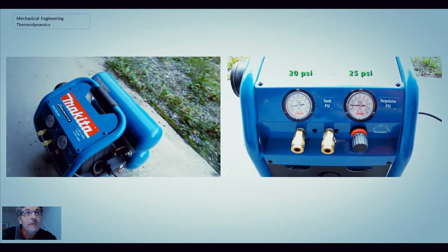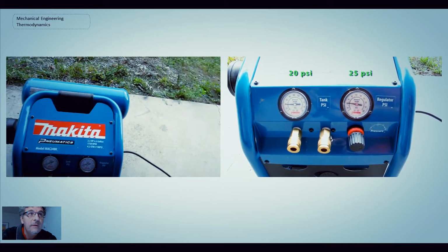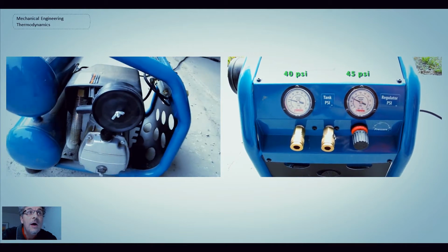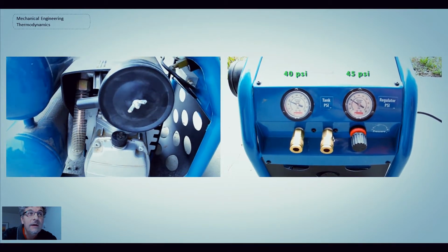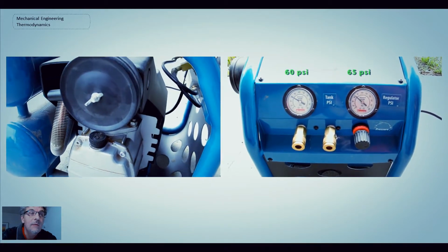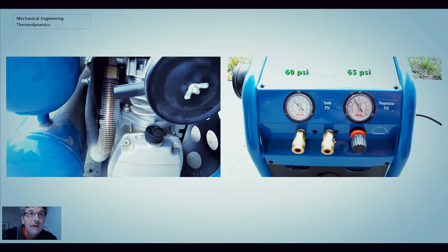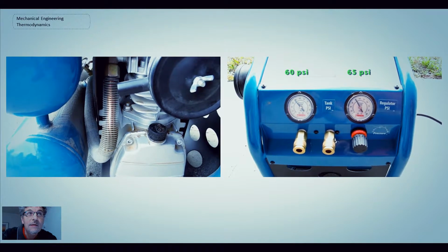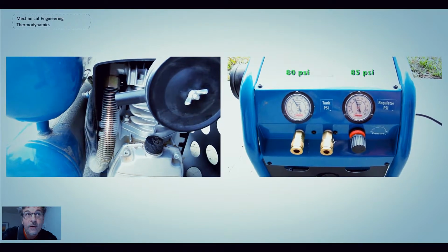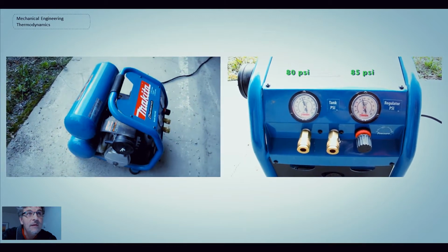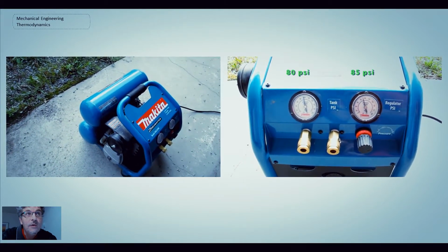As we flip around, you're going to see that, first of all, there's the muffler, there's the crankcase, and the piston cylinder device. There's a copper tube coming out with fins on it. That is the compressed air coming out of the compressor, which is then flowing into a tank. The reason we have those fins is because compressed air gets hot, or compressed gas. And we're rejecting the heat by placing those fins on the copper tube running to the tanks.